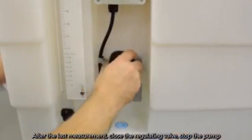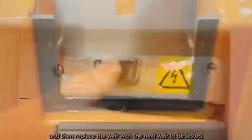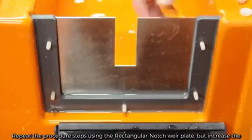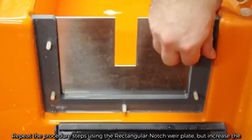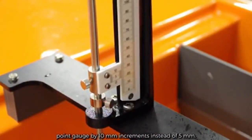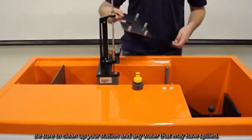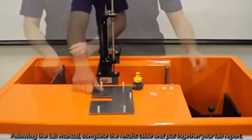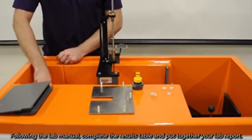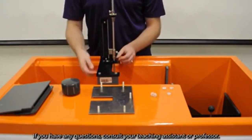After the last measurement, close the regulating valve, stop the pump, and then replace the weir with the next weir to be tested. Repeat the procedure steps using the rectangular notch plate, but increase the point gauge by 10 mm increments instead of 5 mm. Be sure to clean up your station and any water that may have spilled. Following the lab manual, complete the results table and put together your lab report. If you have any questions, consult your teaching assistant or professor.